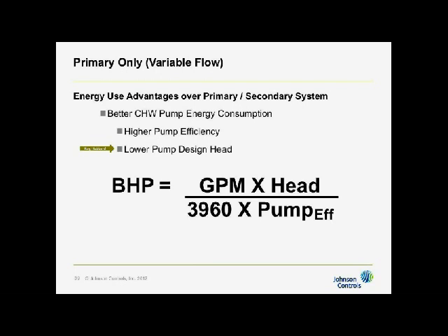And as we lower the head, as you can see in this equation, and we improve the efficiency, the brake horsepower goes down. So between those two items, higher pump efficiency and lower head, I have improved the energy of the pumping system all throughout the year. It's always got something better.